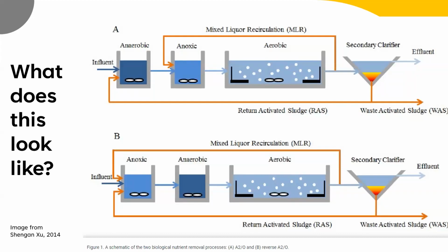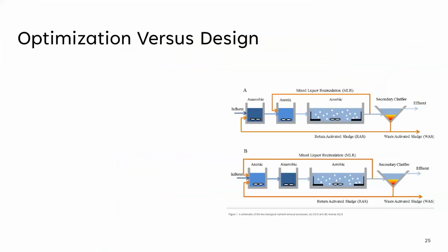Your nitrates, the nitrogen is ultimately being removed from your plant in your anoxic zone, where it's converted to nitrogen gas. Your incoming phosphorus is being converted into biology, and the biology is being removed with your waste activated sludge in a facility like this. Phosphorus is typically more tricky to get right, and then you can also have upsets down the line which lead to re-release of phosphorus. So once you get it in the biology, you need to keep it there as you further process those biosolids and store them in your facility.